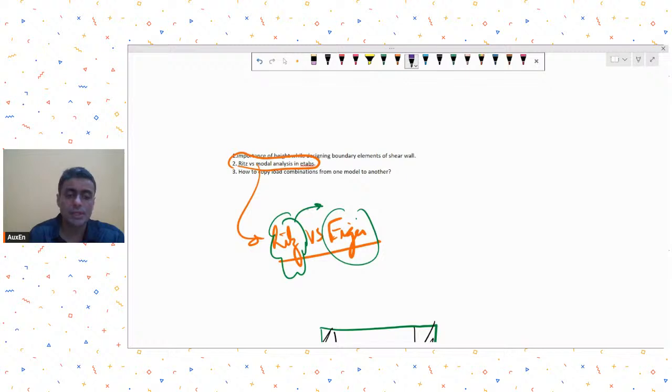So suppose I were to give this command in ETABS: please give me all the modes in X direction which contribute to 80% of mass participation. Understand please. This is the type of extraction I want. I want to extract modes till the modes where I get my mass participation in X as 80%.